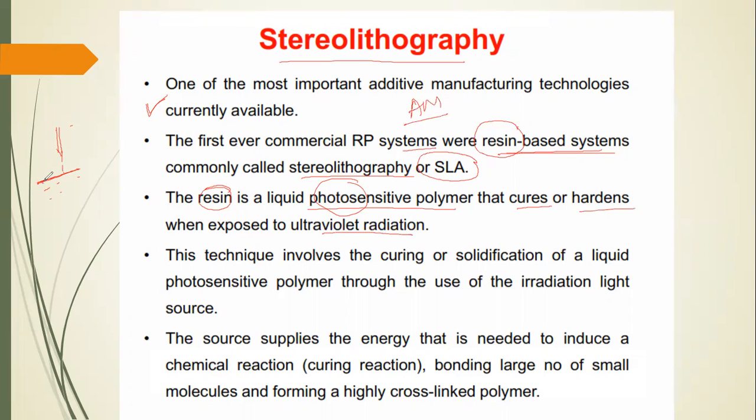So these photosensitive resins, when ultraviolet light falls on this resin, it undergoes curing. Curing is nothing but, it is in semi-liquid or liquid form, so this liquid will be formed to produce a solid.